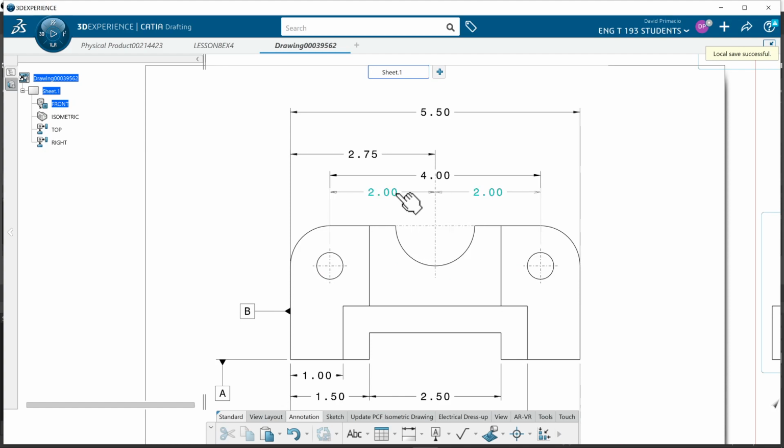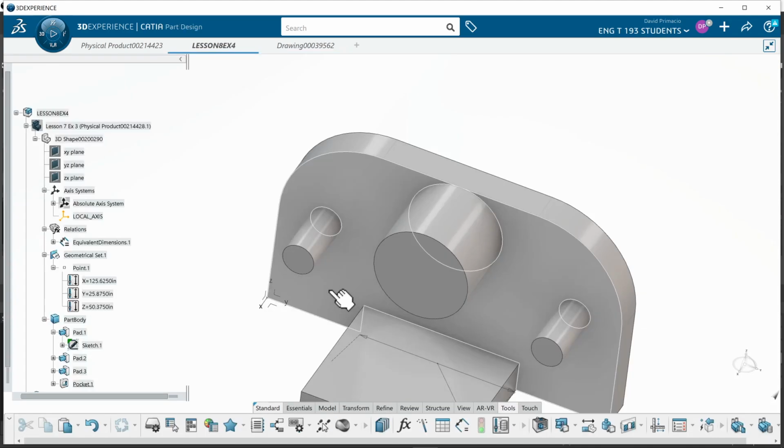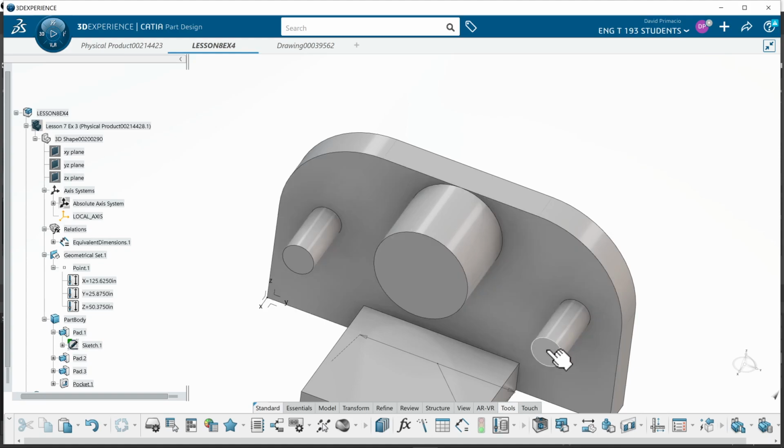This here, dimensioning, again, this could be 2.03, 2.03, and it would be 4.06 apart, or it could be 1.97, 1.97, meaning it would be 3.94 inches apart. So either way, I could be off a total of 60 thousandths of an inch. Now, what if I dimensioned it this way and the shop made it 2.03 and 2.03? It's still within engineering tolerance. And then on the drawing, for this part, they dimension from here to the center and then from the center to here, and they change dimension as well at 2 and 2.